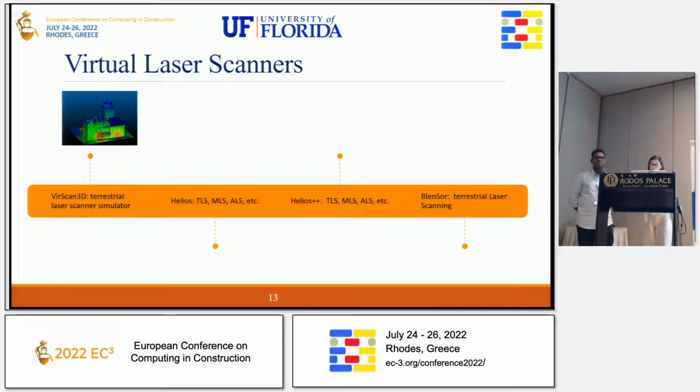The second one is Helios, a library that has a core package and various models that perform different tasks. The platform is mounted with various parameters that can be adjusted to represent specific classes, such as helicopter, multicopter, or a simple linear platform without any movement code. The scene component contains a data structure that holds the scene geometries and materials. A scene in Helios is defined as a triangle mesh that holds a reference and a material definition, able to describe physical properties of the scanned surfaces.